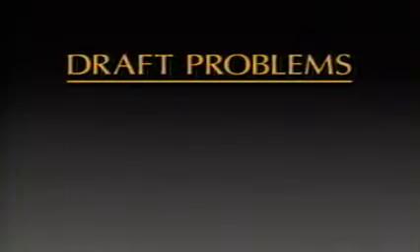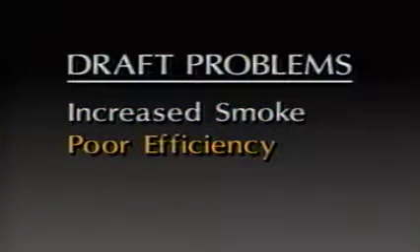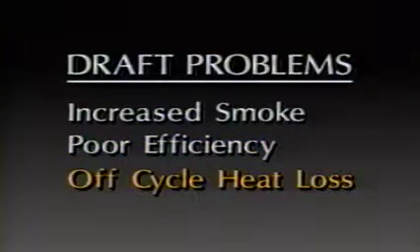With wide draft variations come some very serious combustion problems, including increased smoke when too little draft reduces combustion air, poor operating efficiency when too much draft draws too much air into the combustion process, reducing CO2 and raising stack temperature, heat loss during off periods due to high draft drawing heat up the chimney.